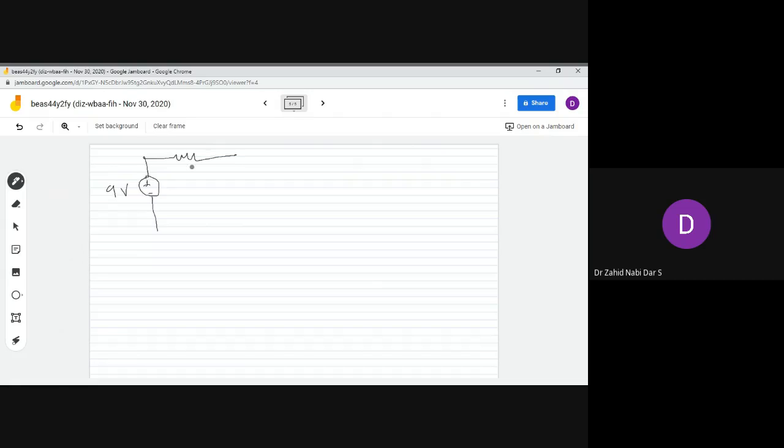There is a resistor. Whenever you see a resistor, there is a fall of potential, and the fall would be like this only. These polarities would not be given. Usually whenever you come across a resistor, take this as my suggestion. There's one more resistor. This is how the problem is given. Polarities are not given in the examination. You may get confused, sir, polarities are not given, so how do we take it? That I will explain to you.